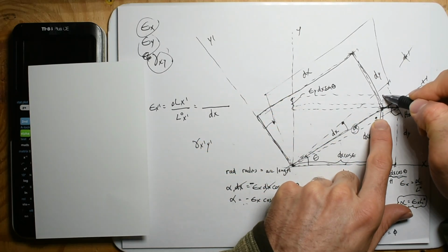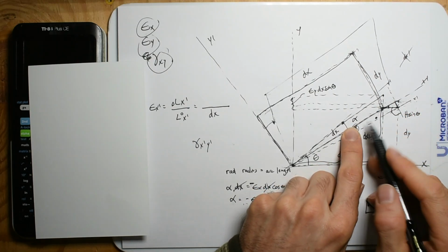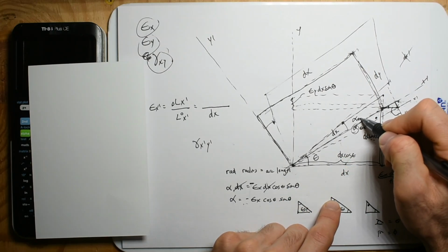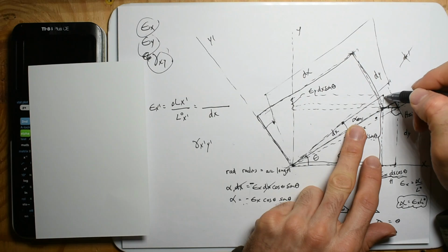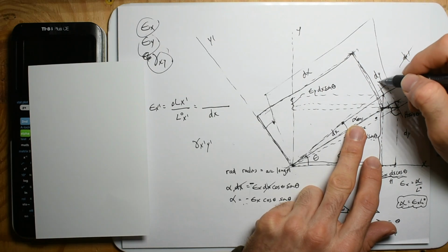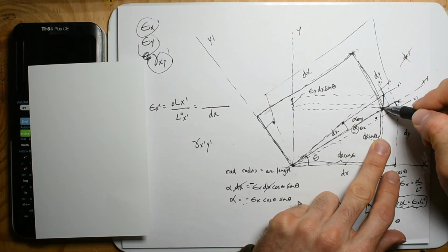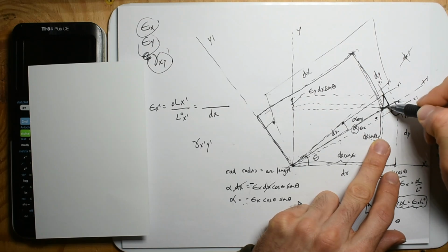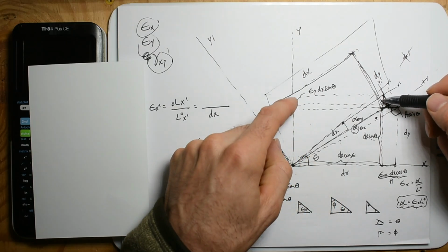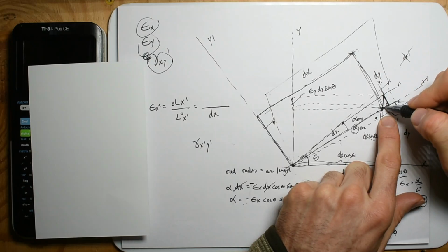And so this point goes up there. This happens. This is our next alpha term. You can call this alpha 1, or you could call this alpha strain in the x. This could be alpha strain in the y, just associated. And this is my new hypotenuse. What I'm going to do is draw in the rotated coordinates, y1, x1. And if this is the hypotenuse, these are the two components, a right triangle. That's going to be the hardest part, but just make sure that this length is a hypotenuse because it's not in the x1, y1 direction. And so we're drawing those components in.